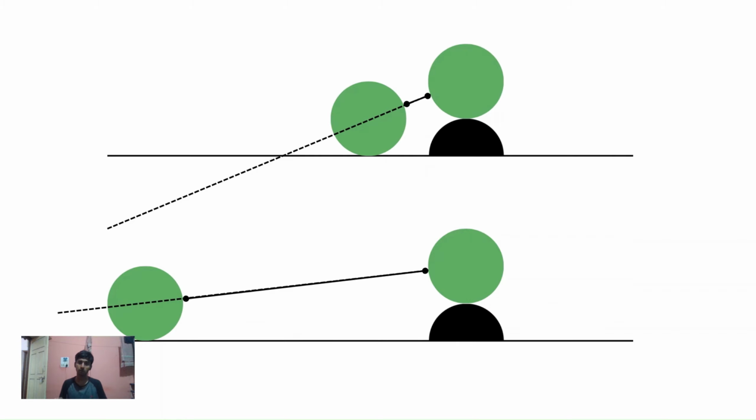The cars with shorter wheelbases will be able to do it more gracefully, because the turning radius of such cars is shorter as compared to the cars with longer wheelbases. If you take a longer wheelbase car and try to go on the same tight curve, you might know the experience that you cannot do the curve in a single go.